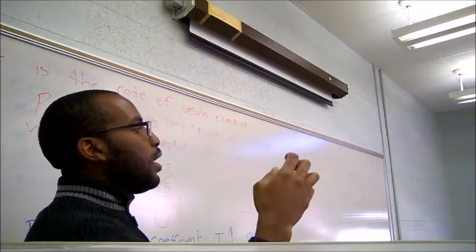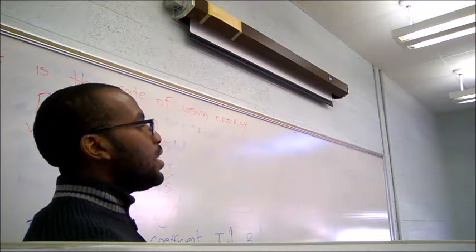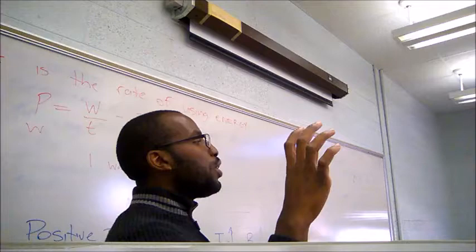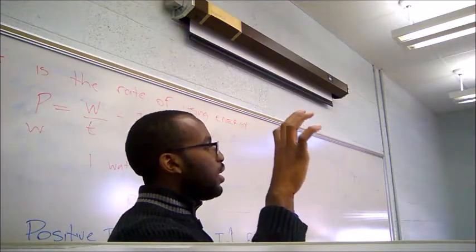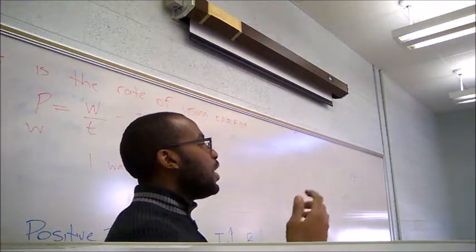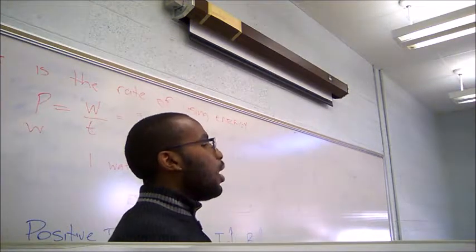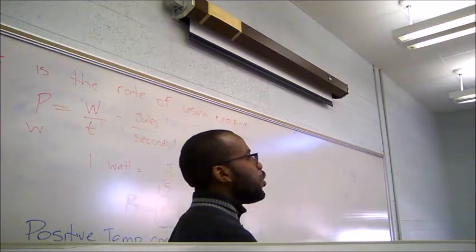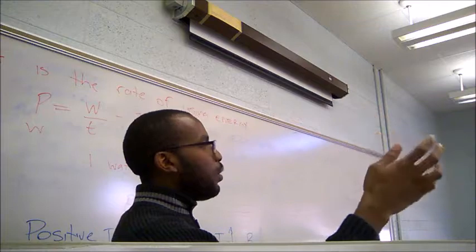So again, we said the resistors are bigger because they can dissipate more heat. We said the resistors convert energy into heat. So the bigger one will be able to convert energy into heat faster or more than the smaller one, so it can dissipate more heat. And most times for components we use ratings. We see that it's rated for a higher power than this one.